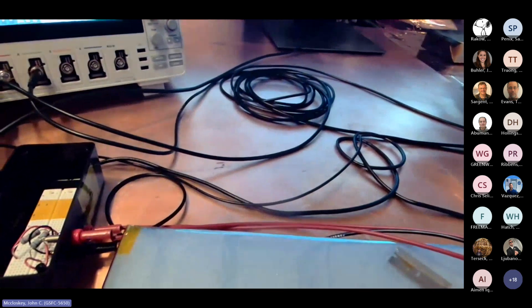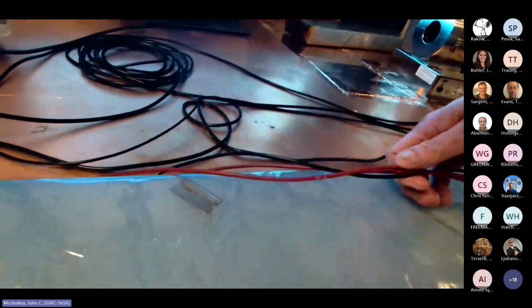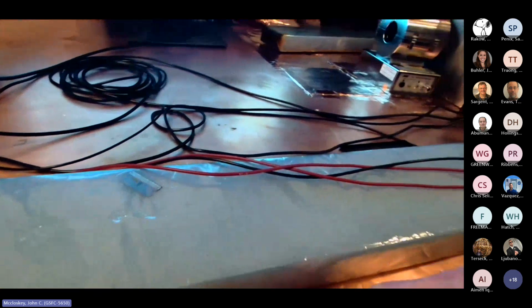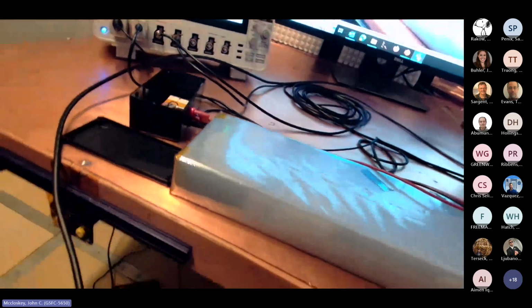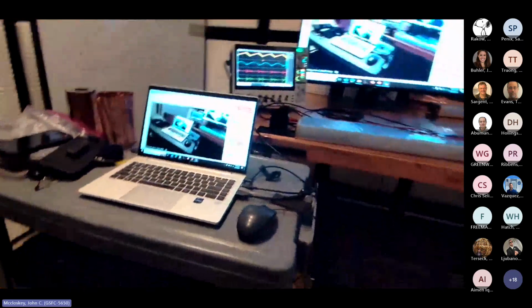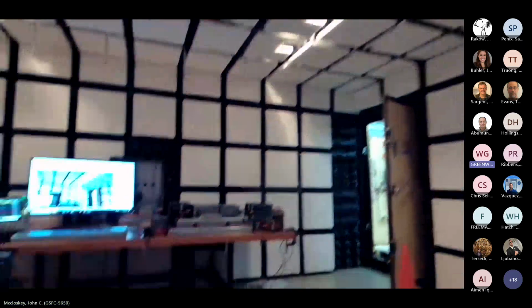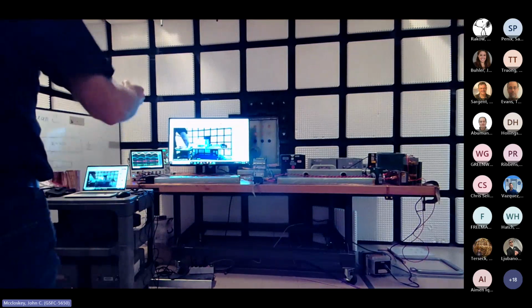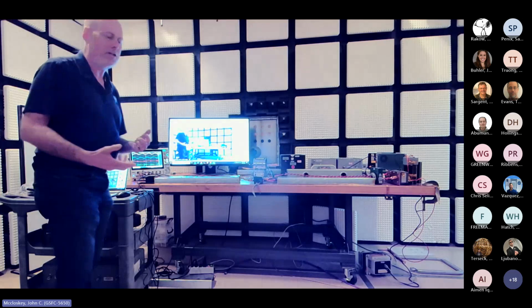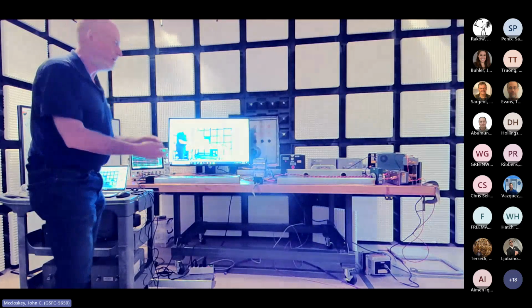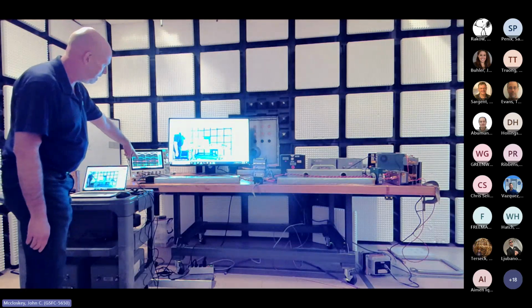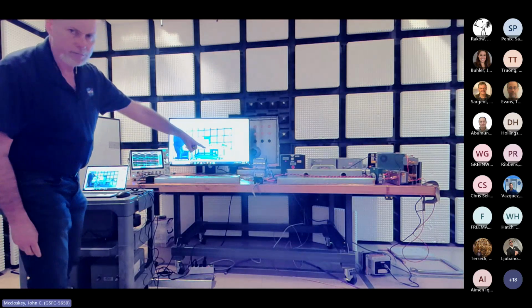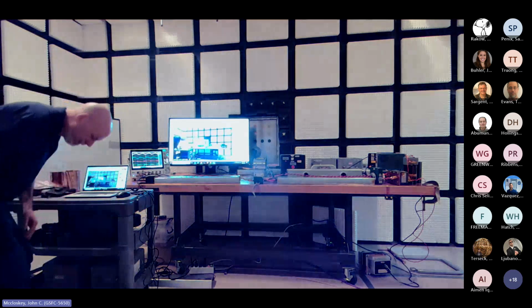So remember that our transmission line is the composite thing. In this case, it's all three of these wires with respect to the ground plane. So do we have a shorted termination of our transmission line with respect to the ground plane? Leading the witness. No. Of course we don't. It's an open circuit termination. So it's a different configuration. It's still a transmission line. It's still a mismatched transmission line, but it's essentially the opposite case. It's an open circuit, which means you're going to have a voltage peak at the far end. And that means your current peak should be at the source end. And that's what we see.